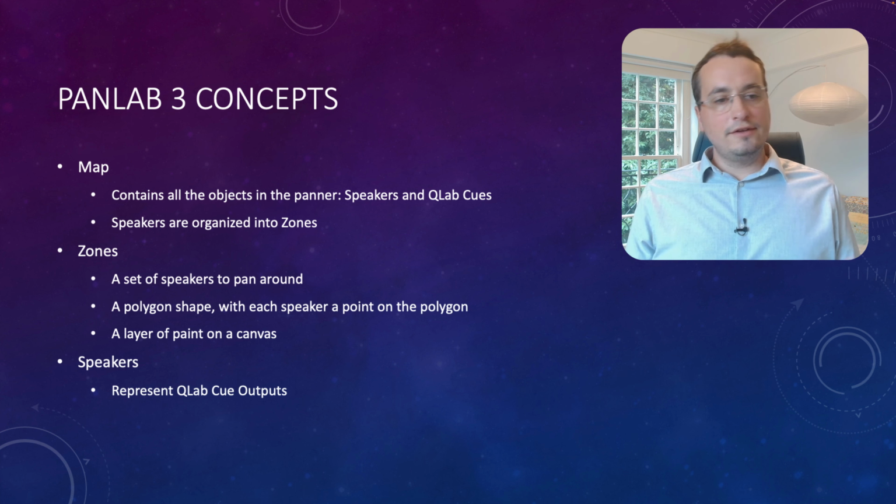I can actually change this so it's the other way around. I can change the order of the zones. If I make this a bit bigger so it's clearer, and drag the front of house zone in this table below the stage zone, you can see that the way those 2 zones are interacting has changed. Now the pink area of the stage zone is above the front of house zone in my visualization here, and that is accurately reflecting how the energy is going to be distributed between these 2 zones.